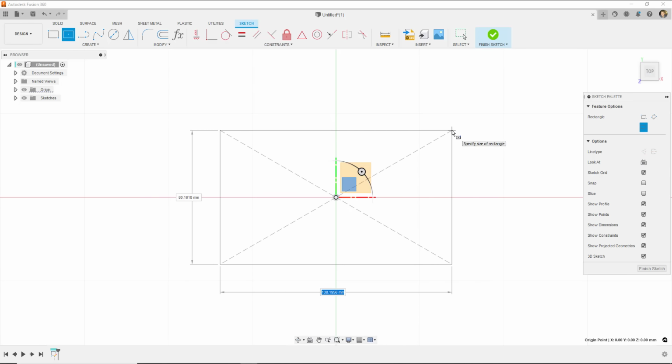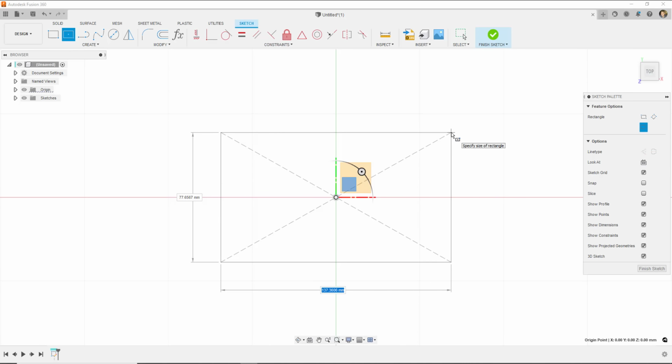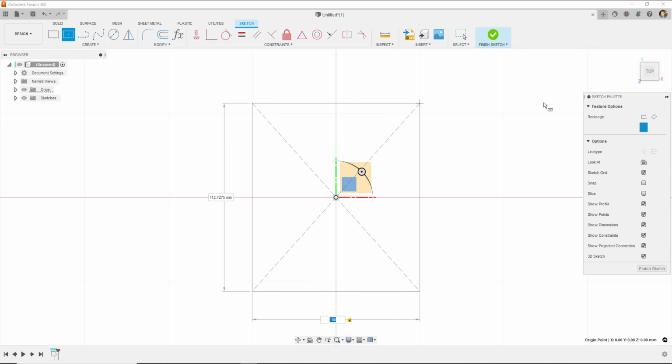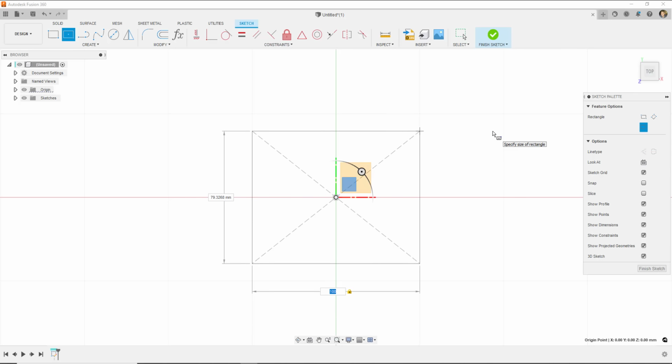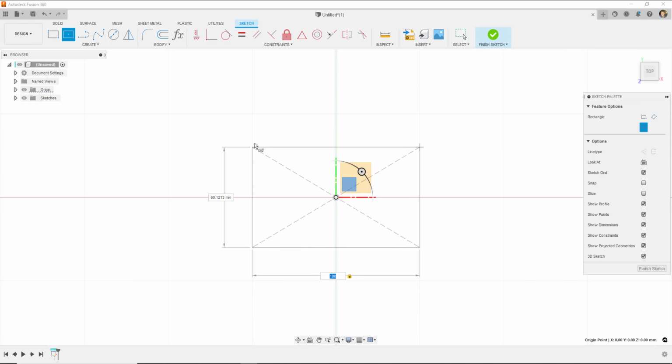And one of these boxes highlighted in blue, that's the current selection. So if you just type in 100, you'll see it puts it in the box. We get a padlock next to it, which means we've locked it at that size. And now we can't change the dimension in that direction because we've told it it's 100. We can only change this one.